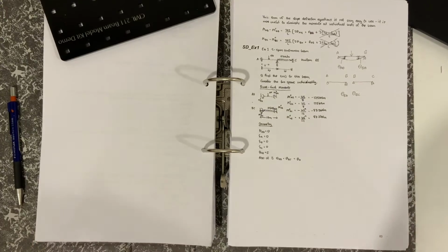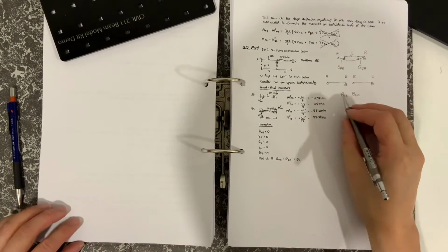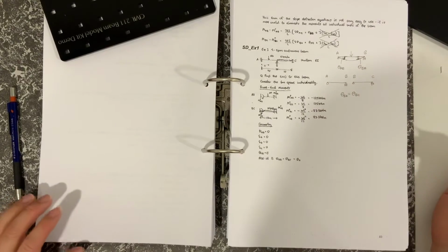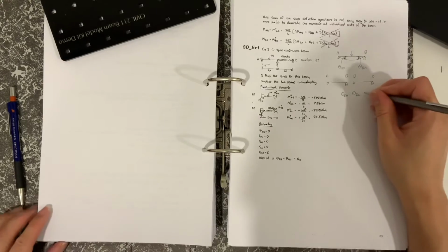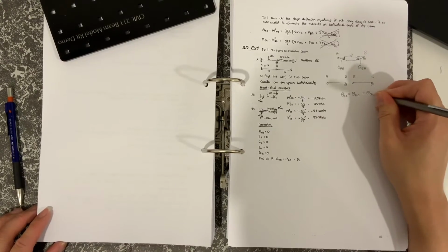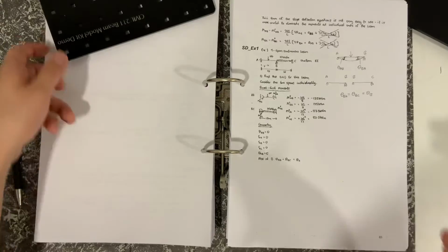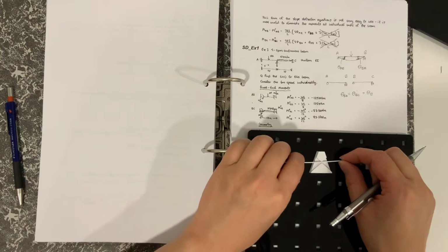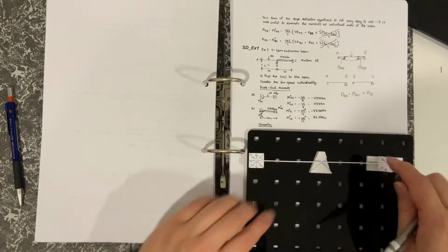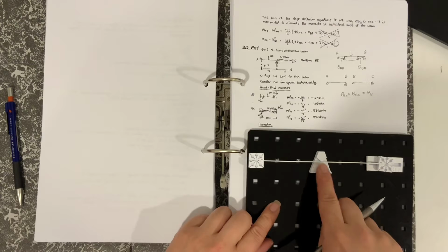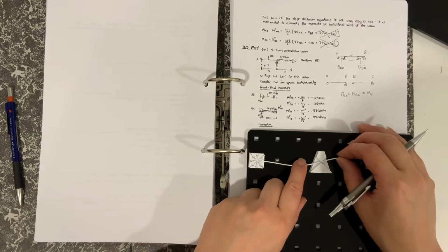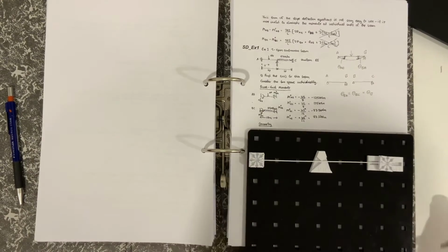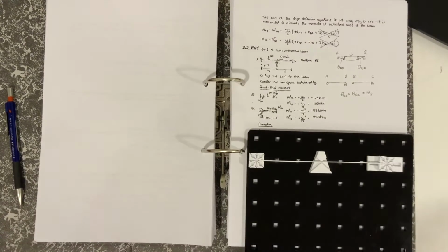But when we solve it, we would find that theta BA must be equal to theta BC, which we could just call theta B. Whether it's a clockwise or an anti-clockwise rotation, we would expect by compatibility at that point that there would be a constant gradient on both sides, and therefore this relationship would always hold.